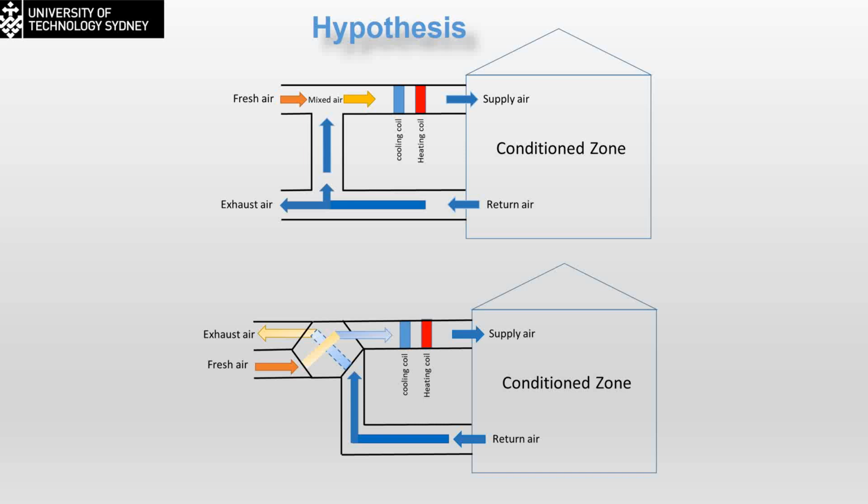No, I didn't compare with them because their system is quite different. It's something like this one, which is another type of indirect evaporative cooler. The one we're using can be used for energy recovery ventilation. This one cannot, because it has one inlet, either the outside air or the inside air, but not both.